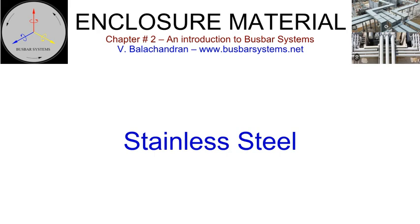Stainless steel sheets are more difficult to work with. Being a hard material, they require special tools, drills, dies, and punches. Metal inert gas or tungsten inert gas welding needs to be performed during manufacture. Stainless steel enclosures are expensive to manufacture and hence specified only for very special needs.